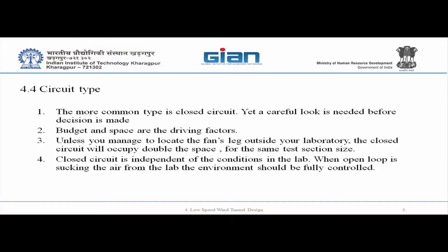If you have the budget and space, you would prefer to work in a closed circuit, because then you don't have to take care of environmental issues. People will not disturb you. Nobody will open the door and change the velocity in your test section. So you control your testing.